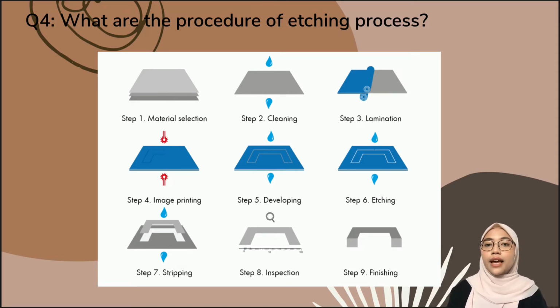Almost any metal and metal alloy can undergo chemical etching. These include steel and stainless steel, nickel, copper, and also aluminium. Almost all metals are etched using ferric chloride, which is a very safe to use, recyclable agent. Ferric chloride can be regenerated and reused.